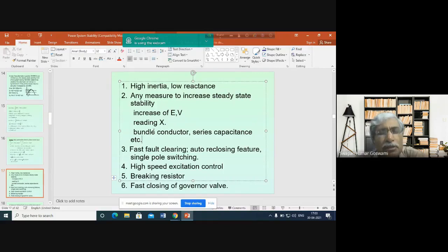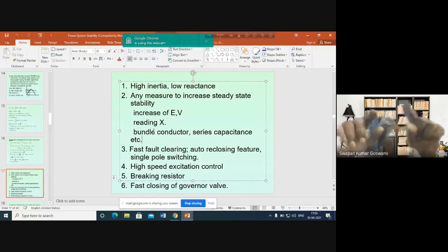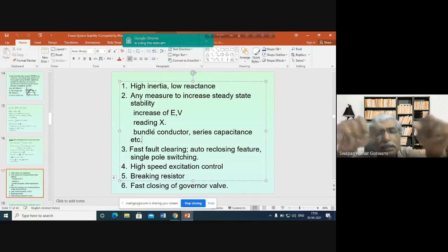So if we measure the total reactance after the series capacitor, there will be a drastic reduction in the effective reactance. The capacitor terminals are A and B. Terminal A is connected on one side, terminal B on the other side. From the generator you have a transmission line, and terminal A of the capacitor is connected. Then on the other end, at terminal B, another line is connected.